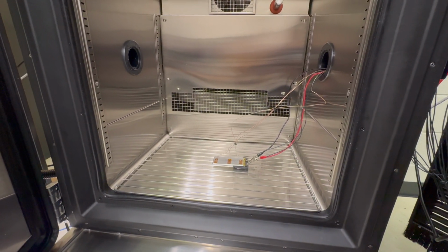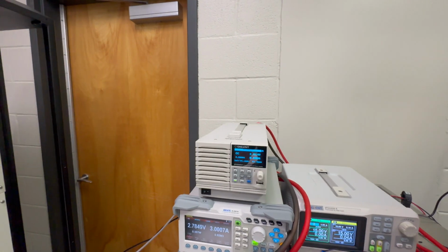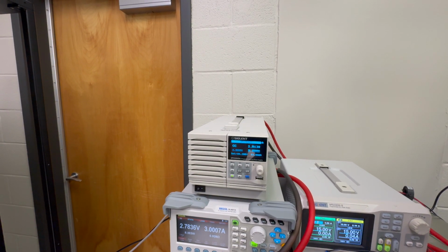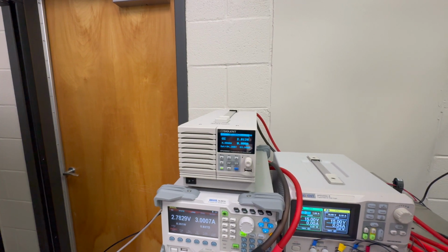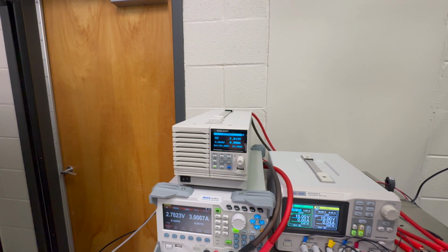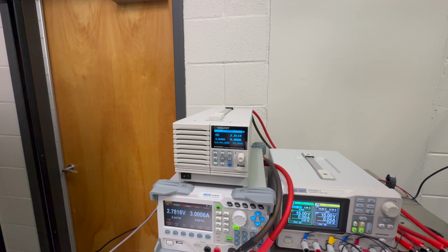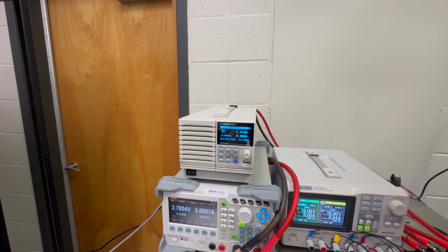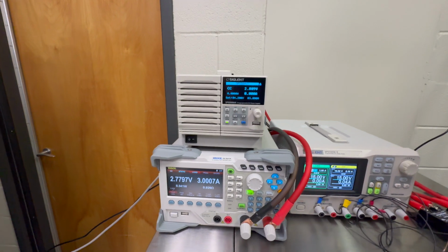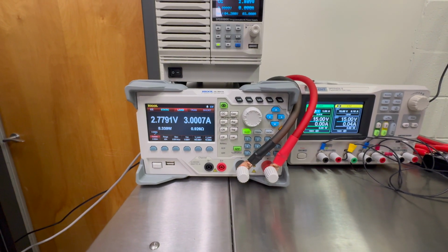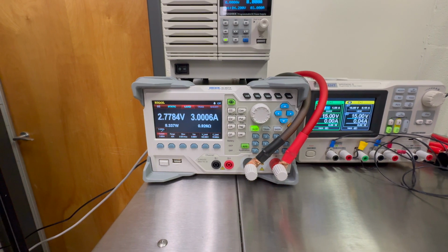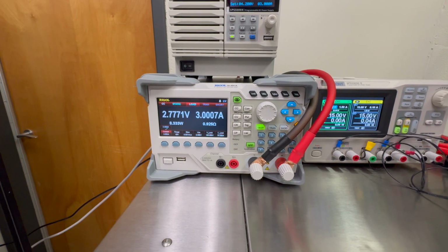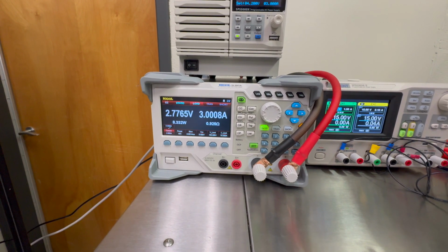At that point in time, we swap over. The power supply swaps over into a constant voltage mode, and we keep monitoring the current until the current drops to about 10% of the rated capacity of the battery, so about 300 milliamps. Whenever that occurs, we know that we have fully charged the battery and we can move on to the electronic load. So we will discharge that battery, as you can see here, at approximately 3 amps, so 1C, until the battery voltage reaches the cutoff voltage, which is about 2.75 volts.